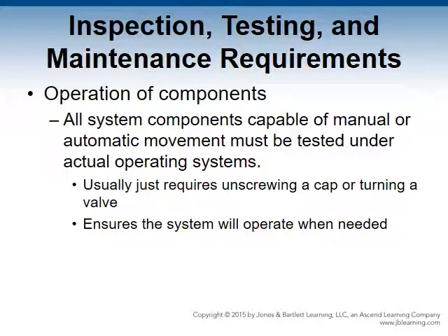Operation of components. All standpipe components capable of manual or automatic movement must be tested under actual operating conditions. For the most part, the components only require unscrewing a cap or turning a valve to move water through the system. This ensures the system will operate when needed.